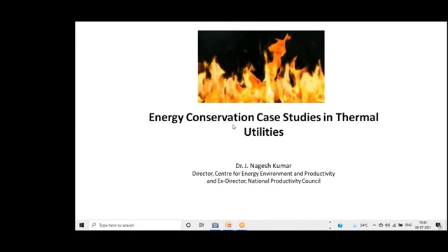If you keep analyzing, the losses can be quite significant. On the combustion side, you burn a fuel and there are unburned losses, the flame heat getting radiated and convected all around, the heat required to heat the vessel itself, and then the control part. How do you know that 90 degrees has been reached?